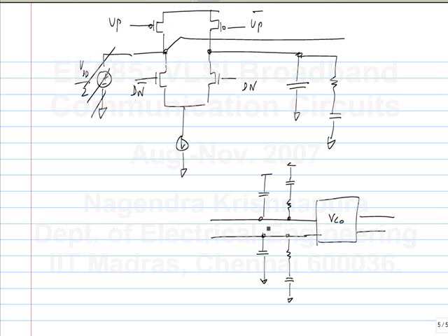So at high frequencies you tend to make a simple VCO with a single-ended control. When you use these electronically variable capacitors like the junction diode varactors or MOS accumulation capacitor, it is convenient to make a single-ended control. You can't make it differential very easily. The control voltage you can't make it differential. But if you do have it, then you make an arrangement like this and drive it with a differential charge pump.